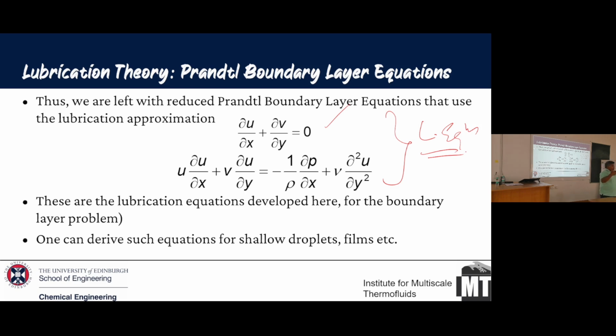That assumes that the rate of evaporation is so slow that it is slower than the time scale of the instability. So at each frozen state, we do a stability analysis. That's a much more intricate, time consuming process, but we can get answers. And for slow evaporating systems, that's fine. But if you have a fast evaporating system, that goes out of the window. So for that, we use a transient growth analysis. That's a different method. I'm going to show that to you as well.